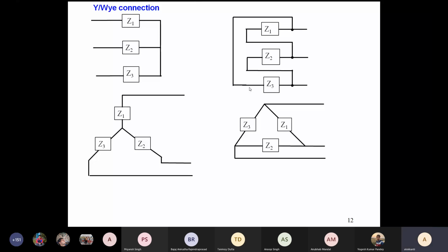But right now we will also see that the load has to be connected. There is no requirement of electrical engineering if there is no load. We all want to run some fan, light some bulbs, light some lamps, or use the electrical energy for some purpose. So there is a requirement of load. This is how the loads can be connected in the three-phase system, either in the star configuration or in the delta configuration. And load is basically an impedance. We know the meaning of impedance: it has a real part and an imaginary part.